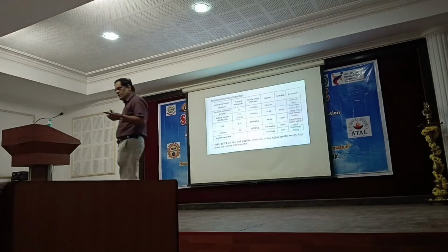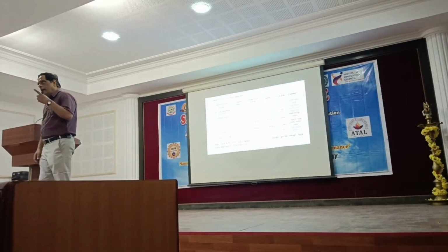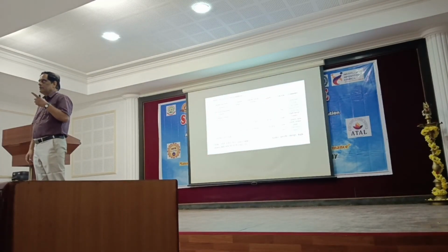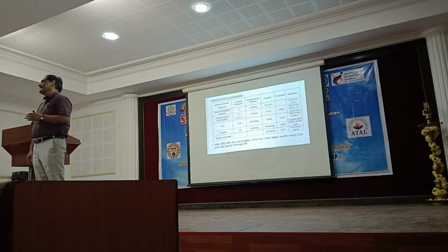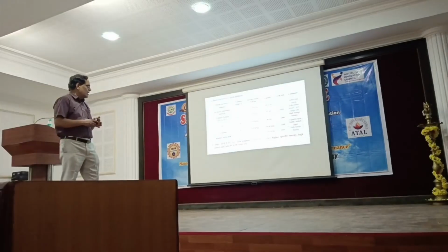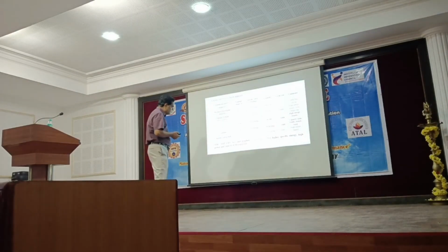Above all, I already mentioned, people are also talking about anode-free lithium-ion battery. When I say anode-free, then what about the role of anode? Your copper current collector itself is going to act as anode. When they undergo reaction back and forth, there is going to be lithium deposition at the copper current collector. That is going to act as anode. When I say anode-free lithium-ion battery, it doesn't mean that there is no role of anode. At the copper current collector, during reaction, lithium is going to deposit. That is going to act as anode for the reaction to undergo back and forth. So people talk about anode-free lithium-ion batteries also.